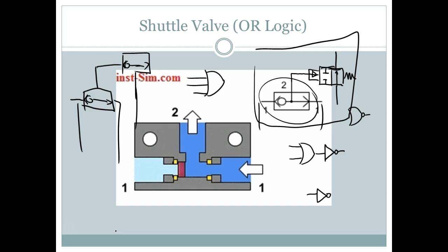We used to have a setup downstairs, and we got a valve over there that's got the setup on it. We had some proportional flow control valves downstairs, but they were for hydraulics, and we don't have that. We don't even have flow meters. So it would be impossible for us to even calculate the speed, because you can't calculate the speed unless you know what? The flow. And we don't know the flow into the cylinder.